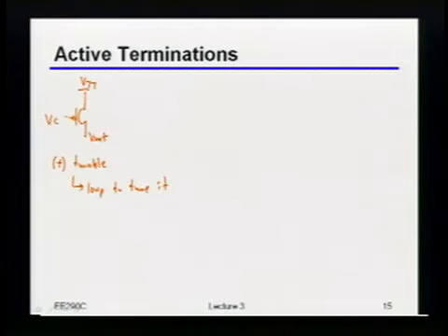Linearity? Oh, I heard. Yeah, it's nonlinear, right? So, and in particular, it's nonlinear versus VDS. Okay. Now, depends on the application. This may or may not be a big deal. But particularly if you have pretty big swings that you're dealing with, that may start to get kind of nasty, right? Because remember, the whole point of doing this was because you wanted a pretty precise resistance. Well, if the thing is nonlinear, then what does that even mean that you made it quote-unquote precise at one particular bias point? Okay? Extra parasitics. Yeah, exactly. It's also got extra parasitics.